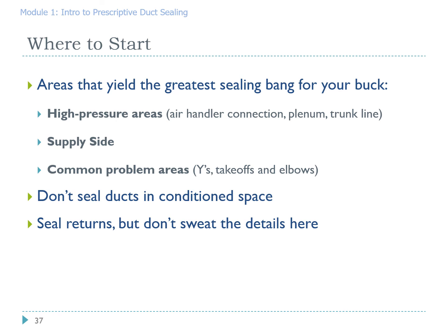Where to start? After you fix the never connects and the disconnects and replace just the rotted out stuff, the best place to start is on the high pressure side. Basically, you can work your way out in both directions from the air handler. The closer you are to the fan, the greater the pressure in the duct system is, and the greater the energy savings will be.